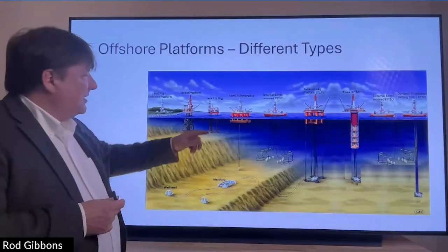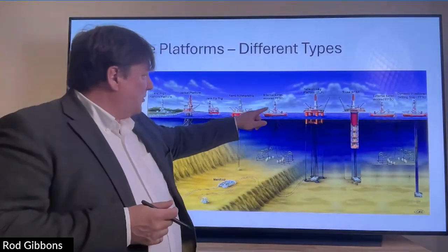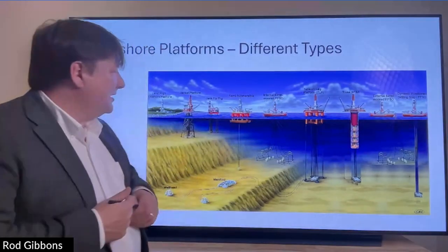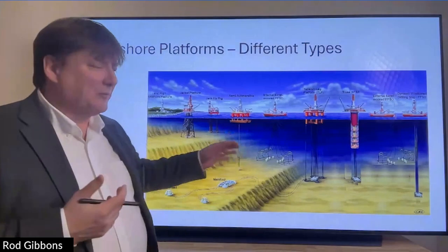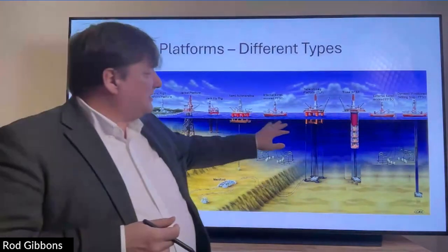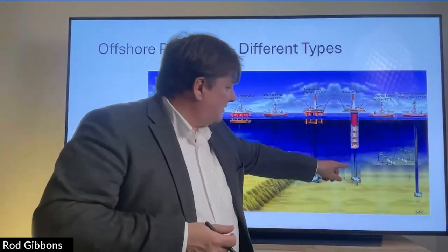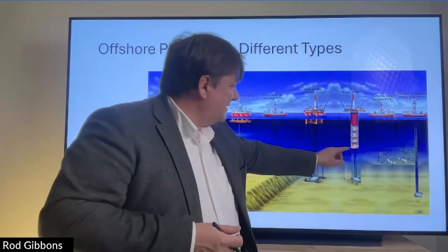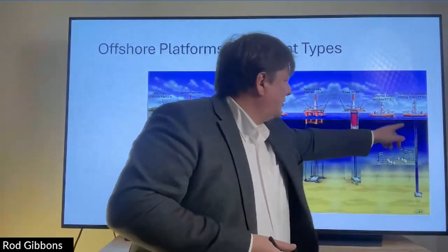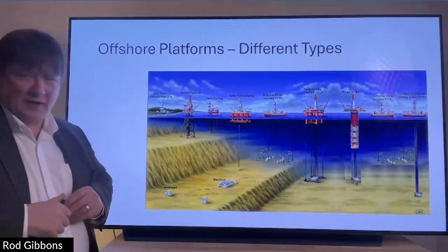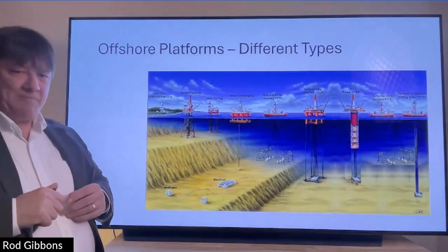Then as water depth gets deeper, you get into a semi-submersible drilling rig and an FPSO, floating production, storage, and offtake vessel with subsea wells. And again, really, it's around water depth and some mid-ocean conditions. And then when you get into deep water, you get tension leg platforms, a spar. So these are floating and they're held in tension to great depths, and then also drill ships for drilling, and also the FPSOs, floating production, storage, and offtake. And we'll just step through these.